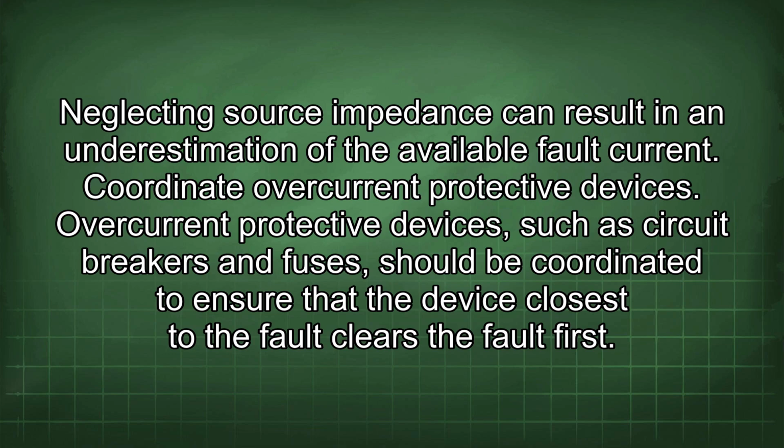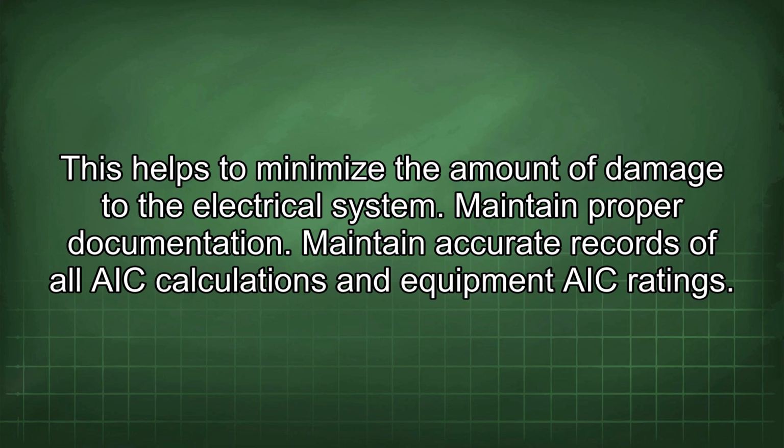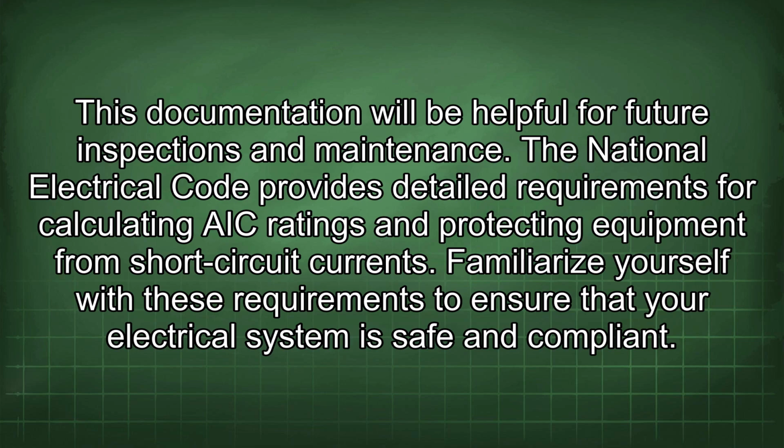Coordinate overcurrent protective devices. Overcurrent protective devices, such as circuit breakers and fuses, should be coordinated to ensure that the device closest to the fault clears the fault first. This helps to minimize the amount of damage to the electrical system. Maintain proper documentation. Maintain accurate records of all AIC calculations and equipment AIC ratings. This documentation will be helpful for future inspections and maintenance.